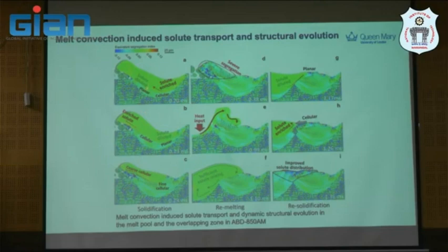This is planar growth because we're talking about a high cooling rate, right? Planar and cellular structure will form. And after that, as this progresses, the solute enriched zone actually goes up and leaves behind the solute dilute zone. And after that, the cross structure, due to the fluid flow as well, will give this cross structure. And you get the severe segregation profile here.